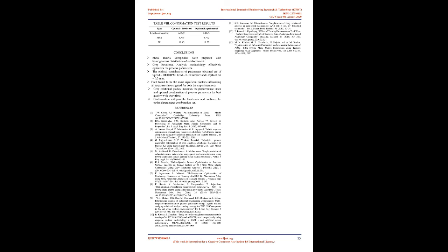5. Analysis of variance. ANOVA is performed to identify the contribution of process parameters on the responses. This is accomplished by separating the total variability of the gray relational grades, which is measured by the sum of the squared deviations from the total mean of the gray relational grade, into contributions by each machining process parameter and the error. An ANOVA table as shown in Table 7 consists of degrees of freedom, sums of squares and the percentage of contribution. From Table 7 it shows that the process parameter feed has the most influence on the gray relational grade, which coincides with the results of Table 5.